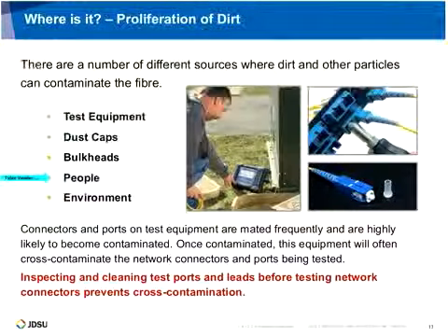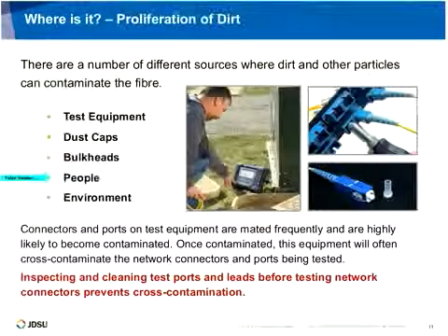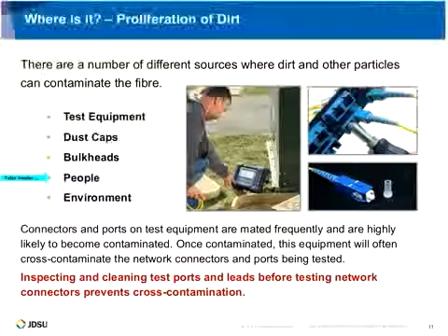The last one, the fifth one, is the environment. Oftentimes in an enterprise situation, you could be in a new construction environment, so the telecommunications room that you're in isn't necessarily set up for being completely pristine, clean, airtight and dust-free yet. You could be dealing with all sorts of residues. That applies both in buildings and out of buildings, especially in outside plant applications. Dirt is everywhere, and these are just five examples of specific things that you should be mindful of when you're working with fiber connectivity.